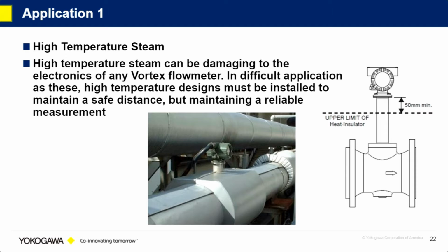Yes, as you can see here, everybody develops a favorite technology for a particular application. I prefer vortex meters for steam service, and to Paul's comment, if I have varying pressures, then I usually go multivariable. It's a direct linear measurement to the flow, so typically compared to other technologies, you have better turndown. It is outstanding as a steam meter, and we can also handle high temperature steam as well. Yeah, it's a good meter.